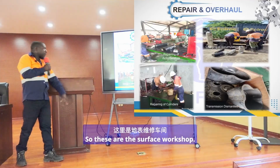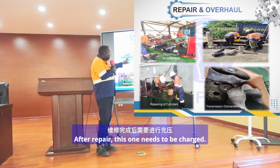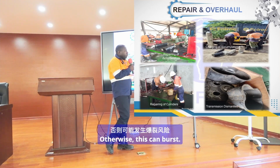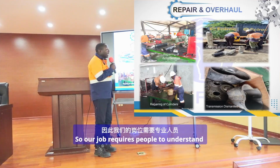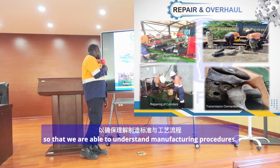So this is the surface workshop. These are accumulators. They are repairing, resealing, changing worn out seals and putting in new ones. After repair, these need to be charged. They are charging here. They need to be precise and understand the charging pressure, otherwise this can burst. So our job requires people to understand, and trained people are required in our department so that we are able to understand manufacturing procedures.